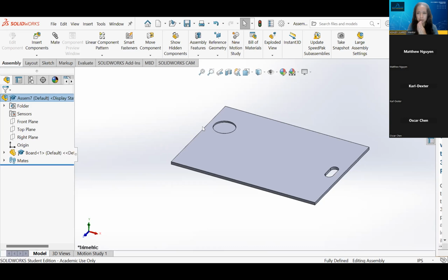Does that make sense? Yeah, so you make it float and then you match the origin with the overall origin. Okay, yes, thank you. I just realized what you said earlier. It was to undefine something. Yes, that's exactly right. Float just allows me to put this in an arbitrary place in space that SolidWorks doesn't know. Thank you. Good question.